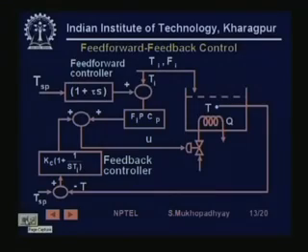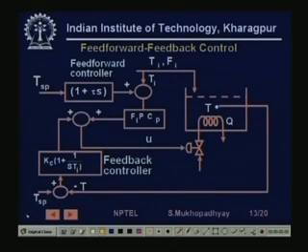So let us look at this problem. What is happening here, first it is the same process. We have the feed forward controller. So we have a T set point which is coming through a command pre-filter, and Ti, they are going through this Fi, this should be rho Cp, and then we are getting U. But now along with that we are also adding another loop.